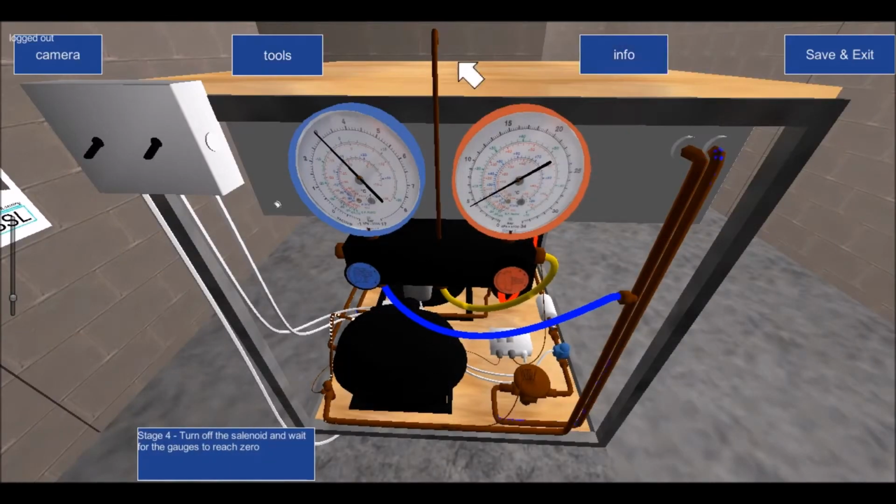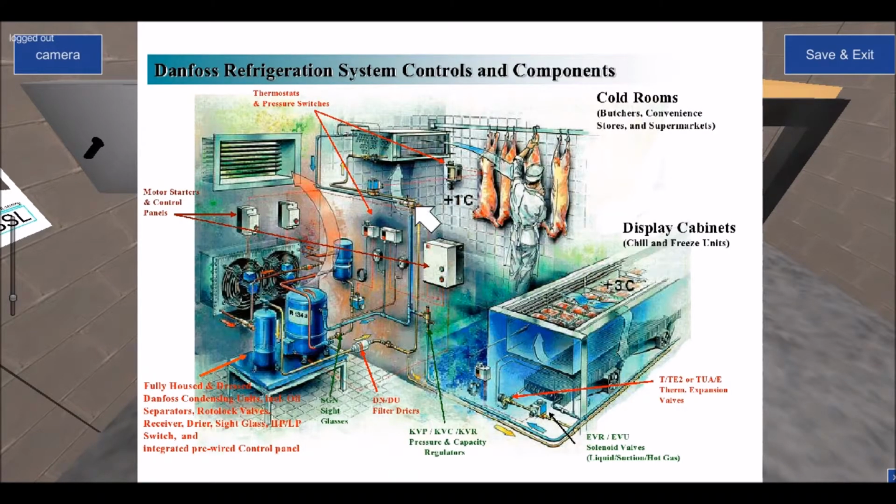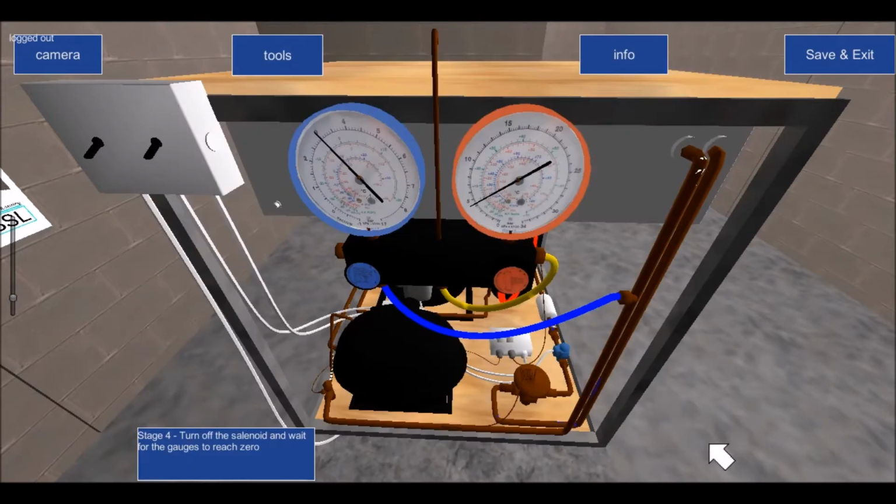Now, what I'm trying to demonstrate is, if we recall when I went to this diagram here, that once this solenoid is de-energized, and it has been de-energized by the signal being broken to it, in other words, the room stat breaks the feed to the solenoid coil. In our case, we just switch it off. So we've now broken the feed to the solenoid coil.